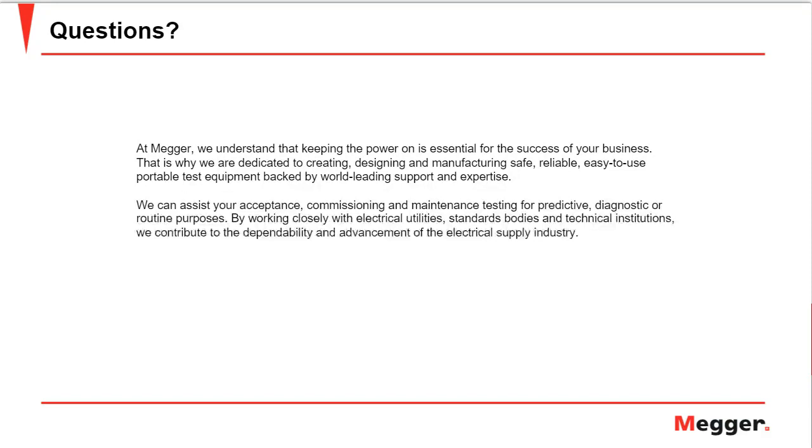And that's very relevant, because one of the first things that a GIC event will cause is a high amount of harmonics, but it will not affect very much the fundamental component of the current. And that's one of the first reasons why the protection elements that we have in the systems are not very much affected by the GIC events.